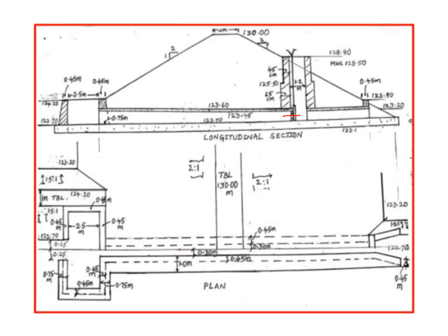So this is the plan at the bottom, plan at the top, whereas the long section has been drawn according to the RLs that we already learned in our irrigation design class. So it should be easy, and I have already explained to you how to draw this tank sluice part, so that it will be very easy for you to reproduce whatever designs you have done, particularly for the extensive survey project, and the same data has been transferred to the drawing sheet.